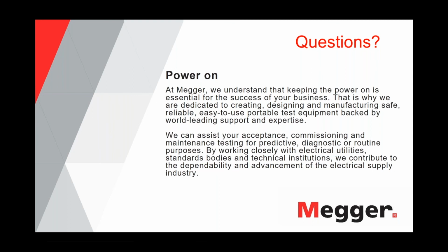So the only thing we can do with that result is some comparison between the phases if we decrease the frequency during the tan delta test. So answering the question, I would say that the shortest would be 82 feet, and, sorry, I don't know the number in feet, but maybe 3-4 kilometers could be the longest at 0.1 hertz.